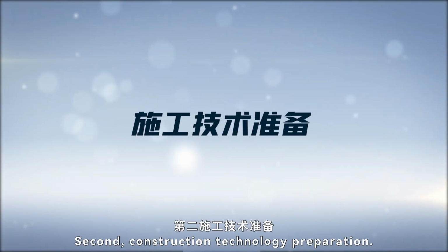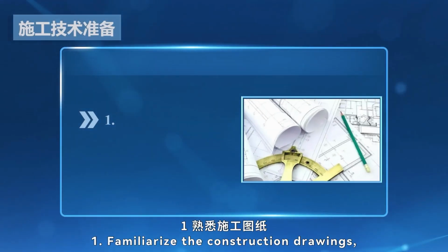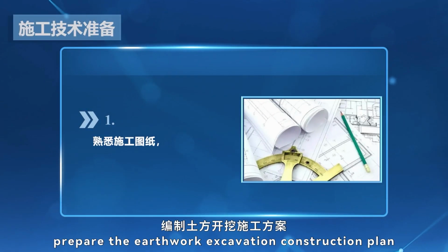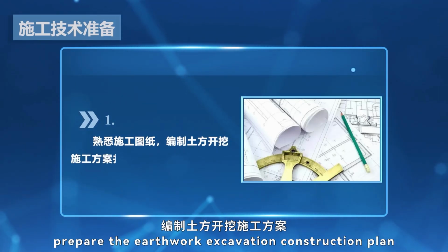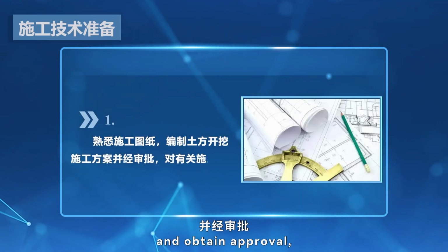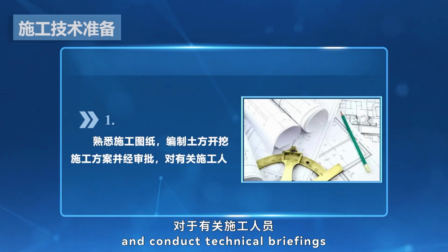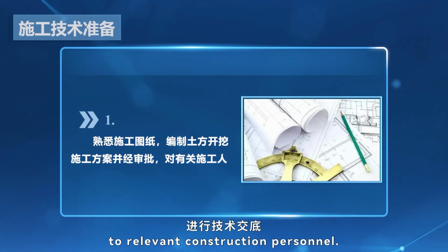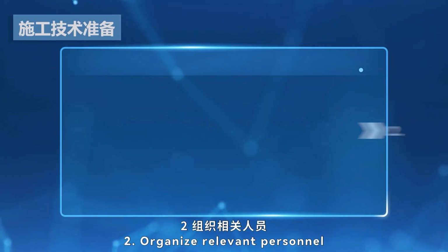Second, construction technology preparation. 1. Familiarize the construction drawings. Prepare the earthwork excavation construction plan and obtain approval, and conduct technical briefings to relevant construction personnel. 2.